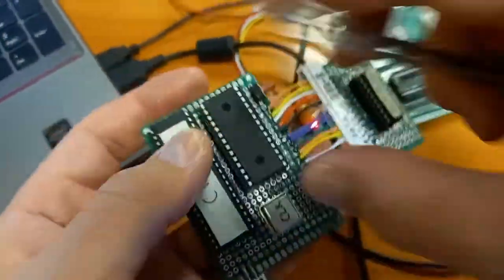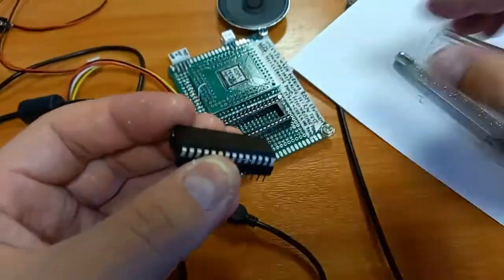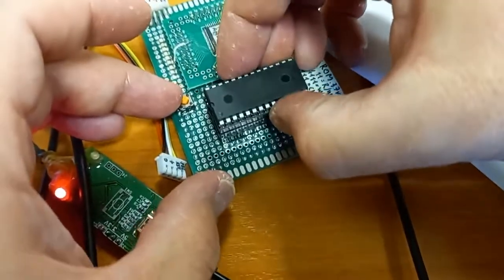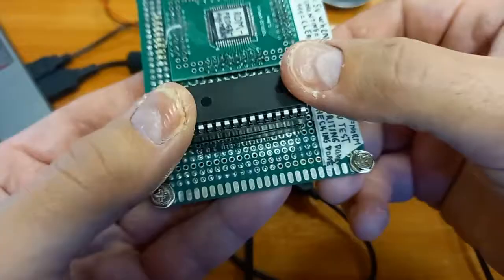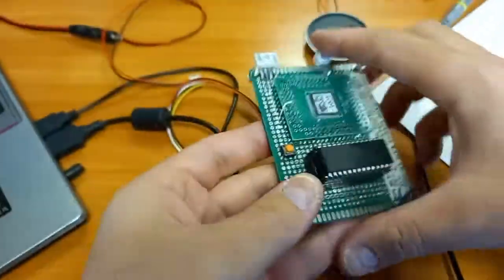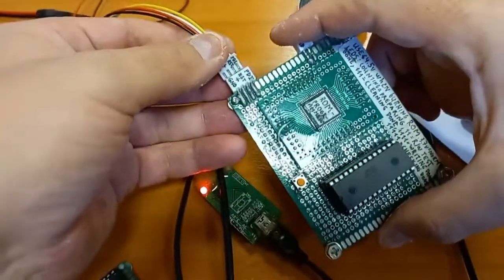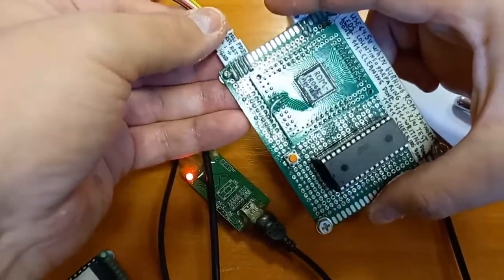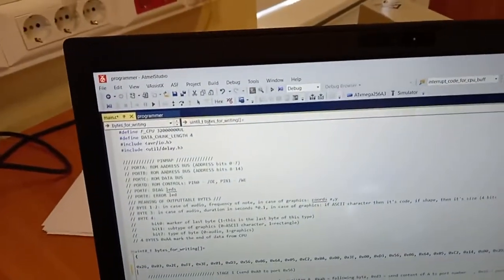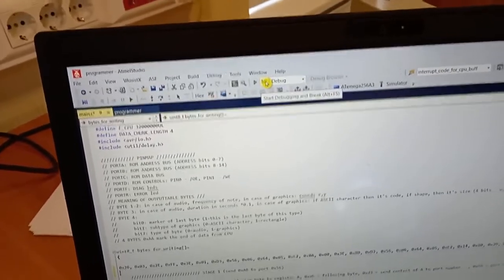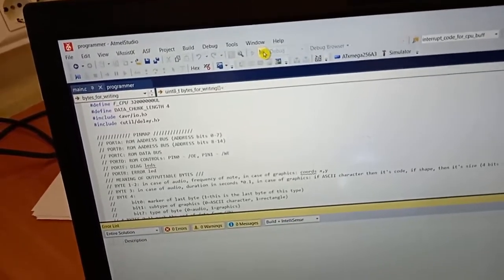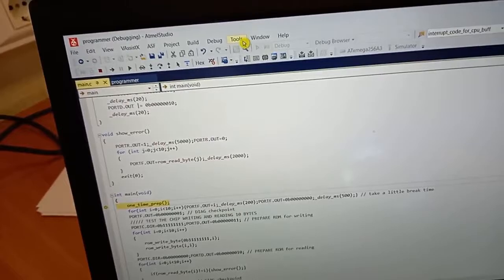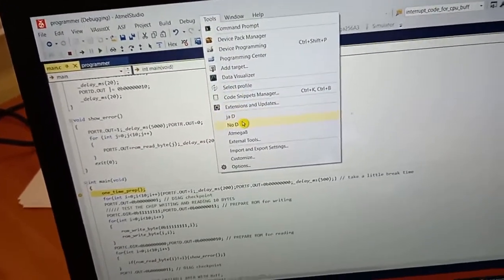255 times it jumps from 1 to 0. But for the first note, it's too fast, it too quickly finishes this 255 times. That's why we have multiplied it by 3 by using the H register besides L. We multiplied L by H times. H, not 8, but H times of L.